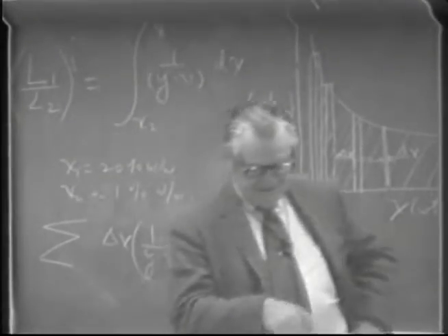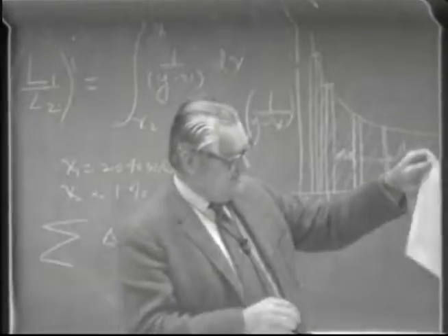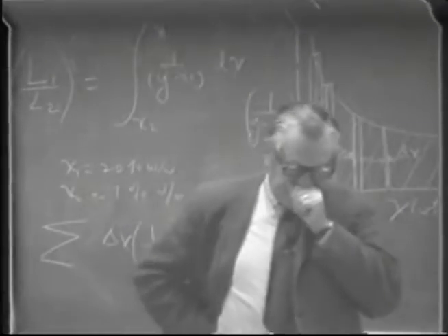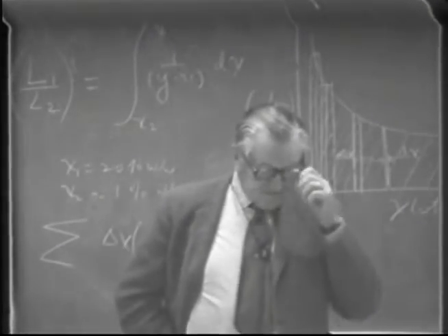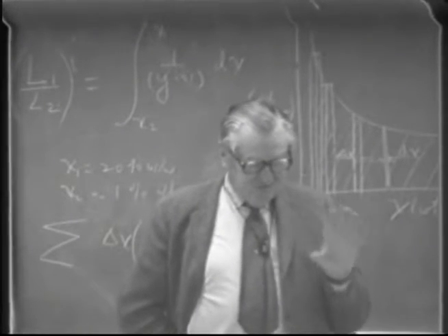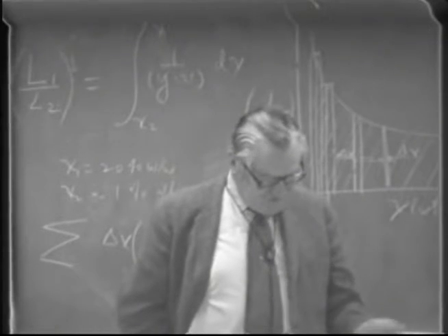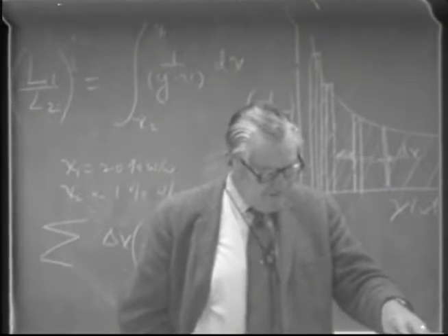I mention here also, which is the beginning of the third page of this, or the last page of this handout, that the temperatures in the fusel oil band are those which correspond to the so-called break. The operators used to talk about the temperature break.